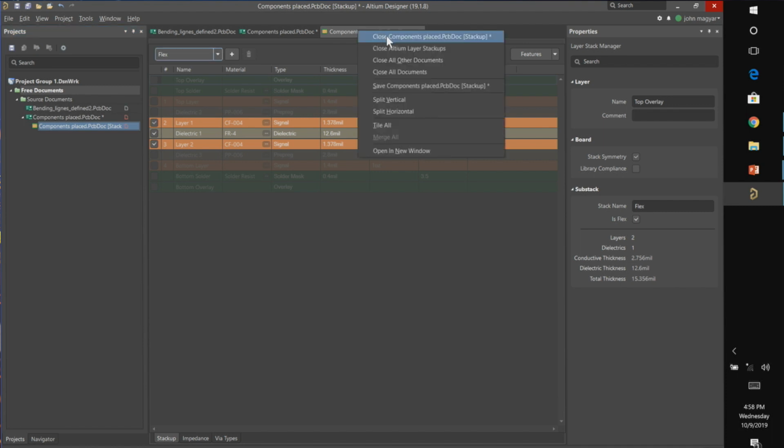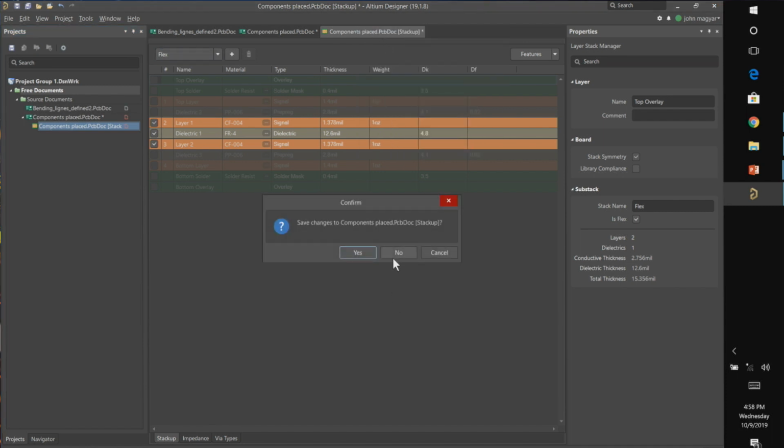Sure. So sometimes we want to expose like a copper layer that's several layers down. Is there, I didn't see a function for like a cutout that goes to only a certain distance, it kind of goes all the way through. Probably the cavity would be the best for that. I know it's on this PC. I'll try to find it. Maybe I've got another presentation after this, but I'll try to find it. So cavity is the object you've got to look into, and that'll help you with components, embedded components, and any kind of opening that extends through.